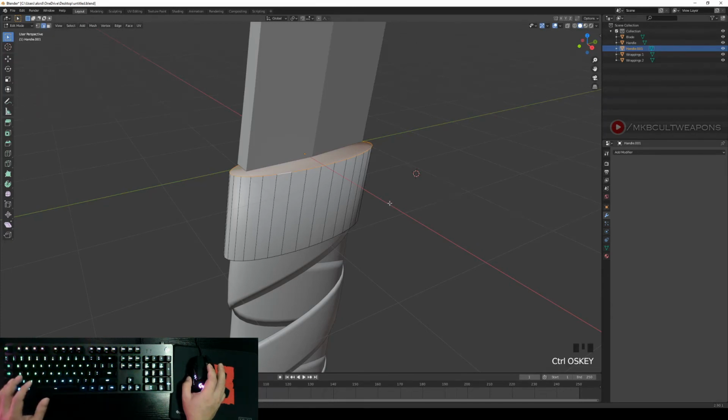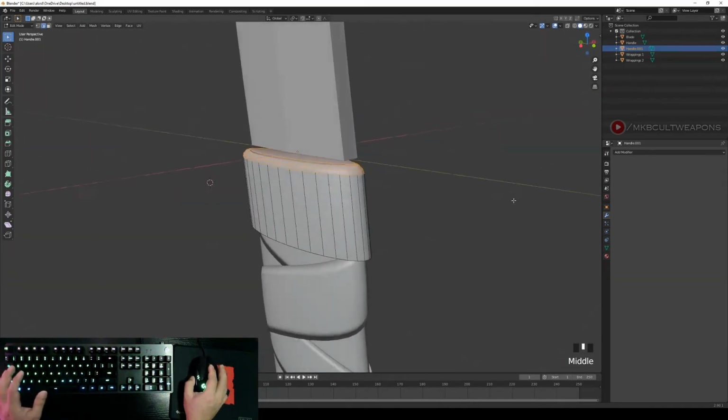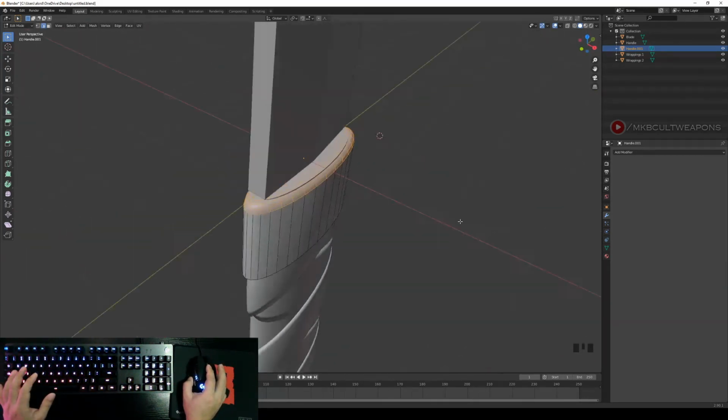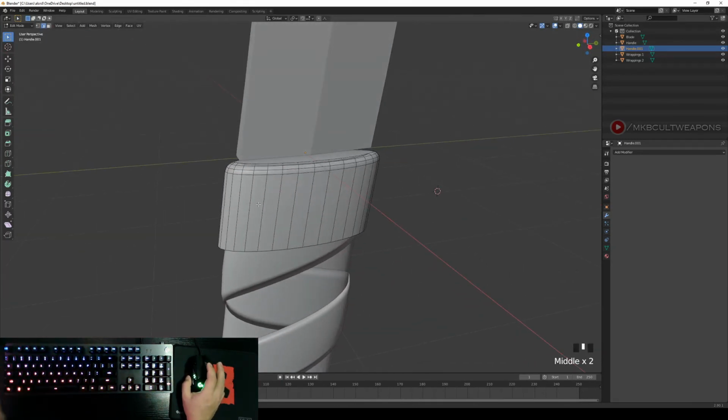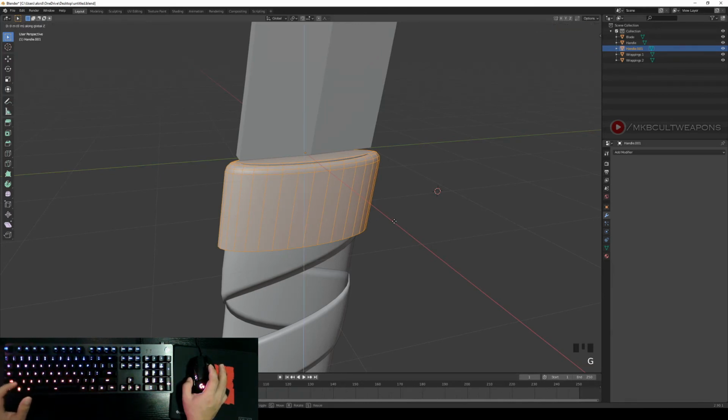what do we call this again? Control, I think that's Control B. Yes, that's Control B. Okay, let's press Control B and move your mouse a little bit and scroll your mouse wheel so that we will have that kind of, what do we call this, transition there. Let's just move the entire model upwards by selecting A, then press G, then go to Z axis. Perfect.